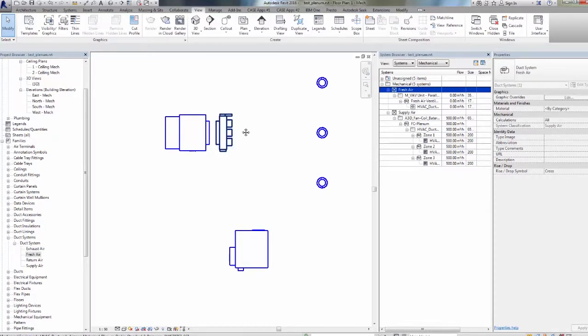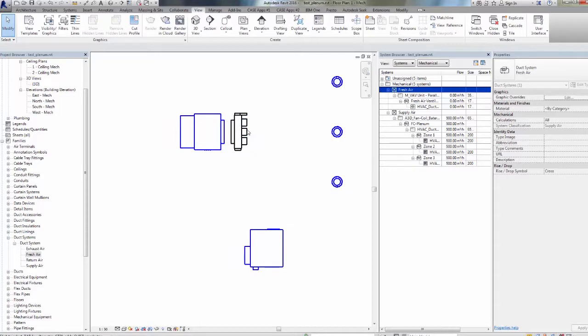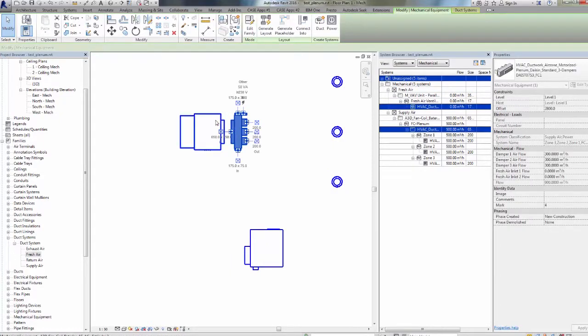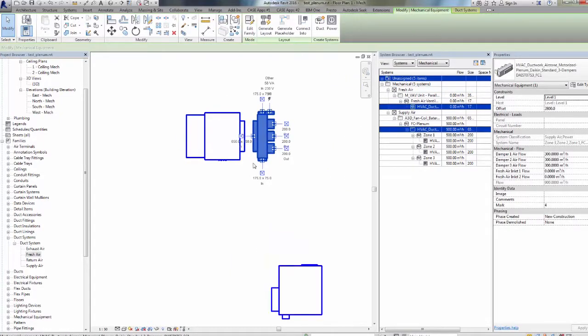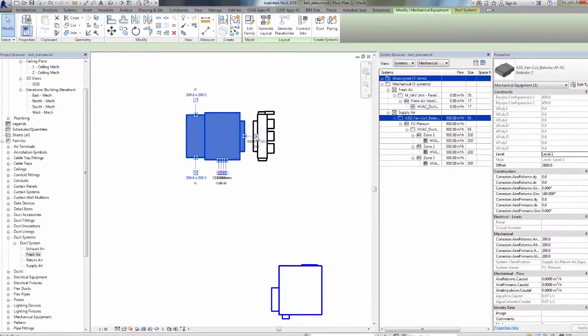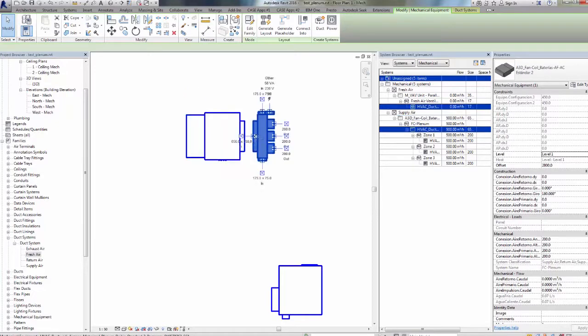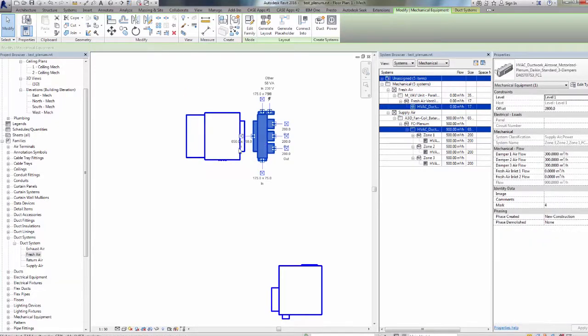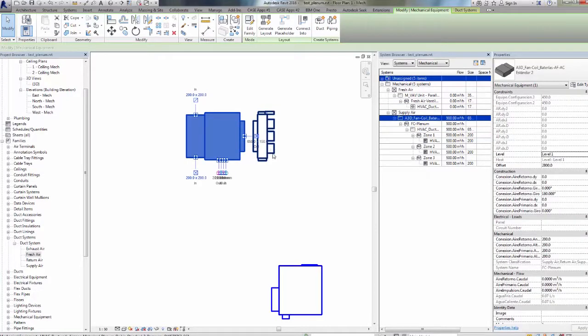First connection that has to be created is the one from the plenum to the indoor unit. If the alignment and the resizing of the connector have been correctly performed, both connectors must be categorized as air supply, but the plenum must be in while the indoor unit must be out. Once we confirm it, we'll see how the plenum will move, but not the indoor unit.